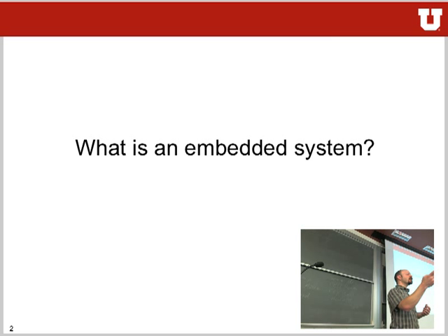So he said a cell phone contains a lot of different embedded systems. That's absolutely correct. For example, the baseband processor in your cell phone is most likely just doing the baseband processing of your cell signals. It's not a general purpose system. It doesn't do the video graphics, for example. It's there for the communication. We have the Wi-Fi chip. It's actually a really good one. Modern Wi-Fi chips are little embedded systems. They have small little microcontrollers in them. They have controllers in them that can run code and do stuff with it.